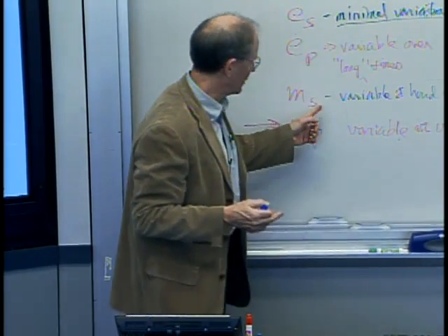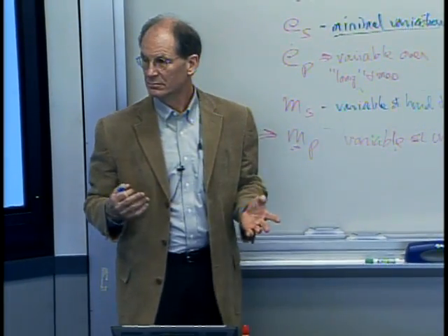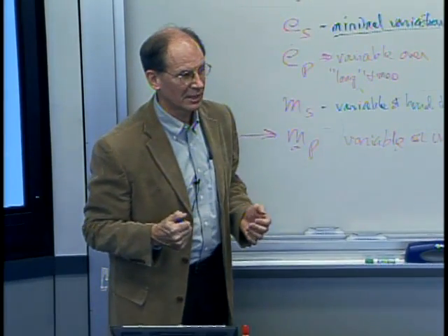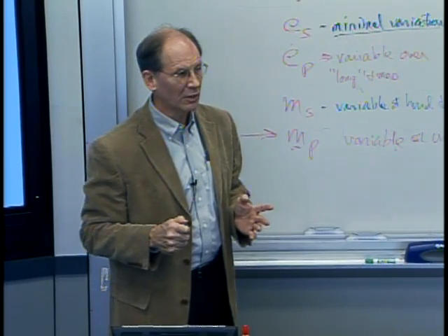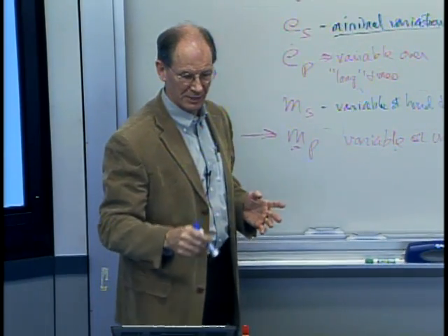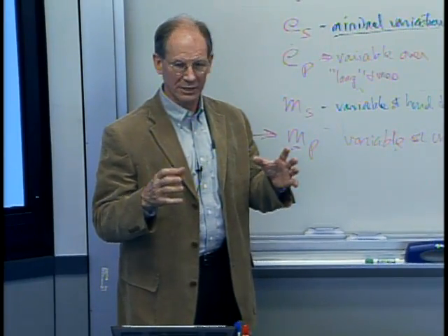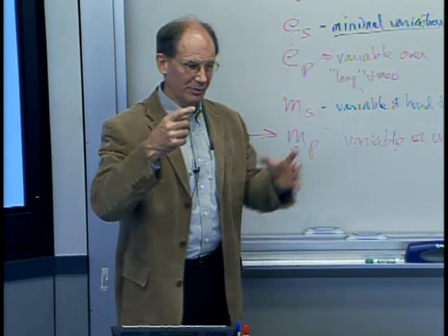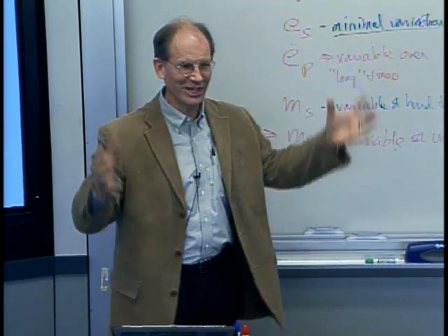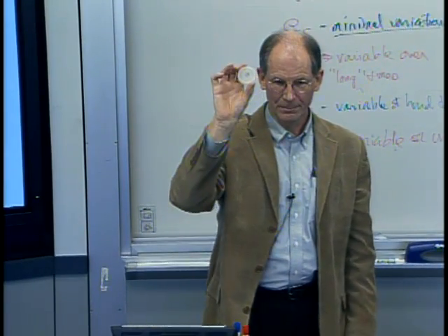That's a state of the polymer, right? It's a thermodynamic state of the polymer. I don't know. Unless I measure it, I don't know. I'm not controlling it anymore. Now, there are also cases, and this is true, I think, in the semiconductor world now more than anything else, where if I want to control a temperature, for example, I don't measure the temperature of the oven or the chamber. I measure the temperature of the thing that I'm going to make.